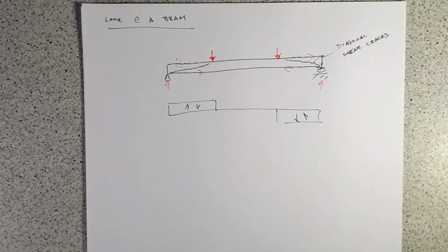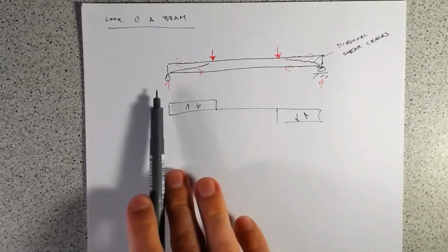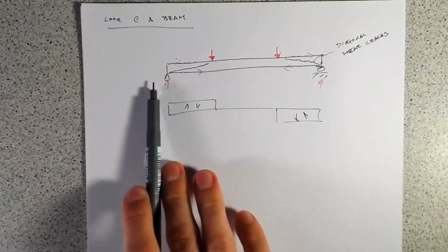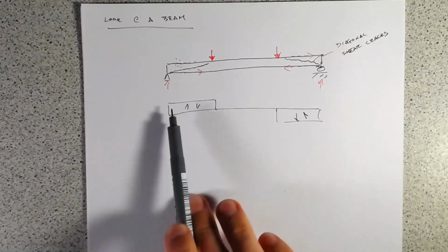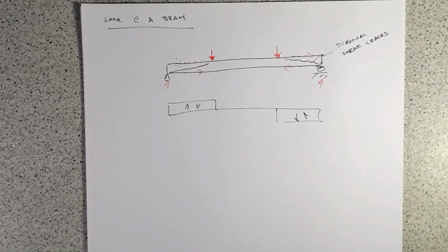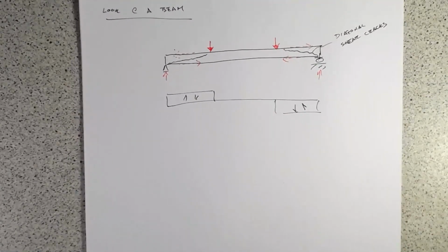One of the next things we're going to look at is, we've got these two stresses, but we also have bending stress, which is essentially a normal stress, right? It's uniaxial. Here you've got compression on the top, tension on the bottom. Those have to add up with these shear stresses somehow.